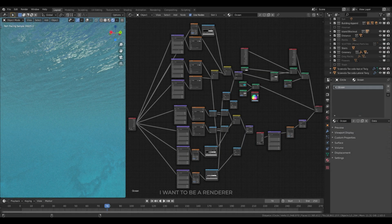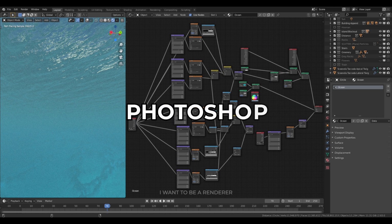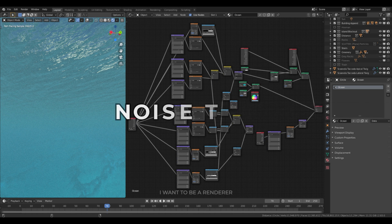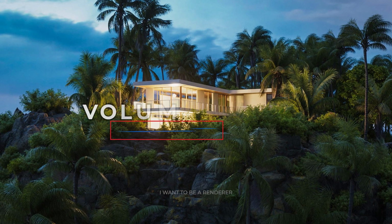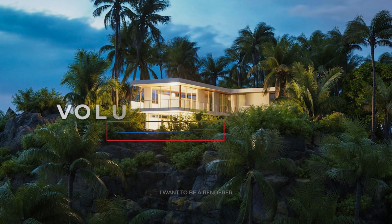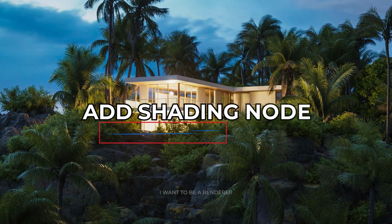Blender has an ocean simulation modifier, which he used to create a couple of normal maps that he made seamless in Photoshop and then combined them using RGB mix nodes with noise texture to break the repetition. To replicate the clear water, he did it with the 3D software using volume absorption and added a volume scatter node that he mixed with the previous one using the add shader node.